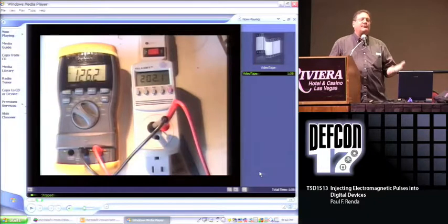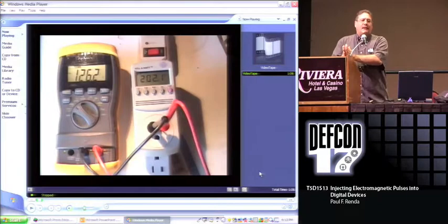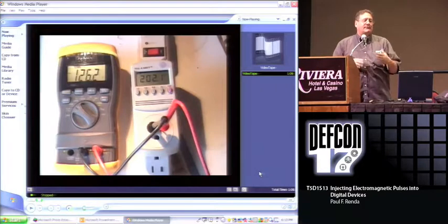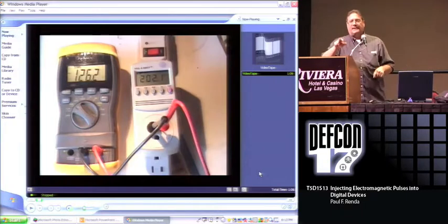Also use batteries. Don't use a power supply, an electric power supply, or a regulated power supply, because that power supply is going to go down. What happens is that unless you have the impedance matched up perfectly, part of that pulse is being reflected back at your equipment and into the 110 wiring of your building. Use batteries, period. I guess I didn't answer your question, but the solid-state device, I would not try to control through that. I try through a mechanical type of switch.